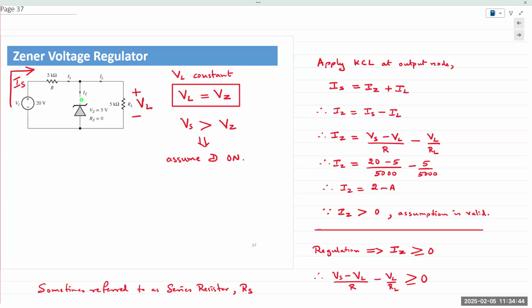That was for the ideal case. So if, let's say, the voltage here was 4.9, then everything is going through here. Nothing is going to the Zener diode. Is the Zener current dependent? In a way, but we'll mostly use voltage for the initial analysis.